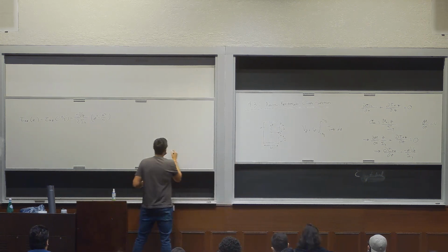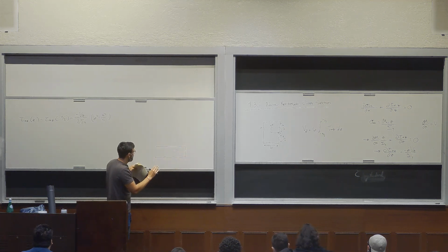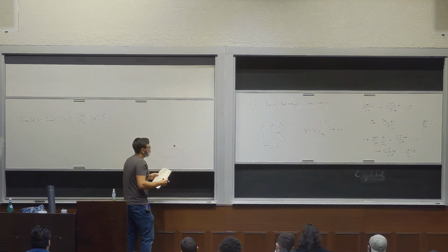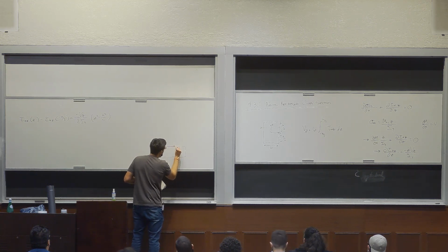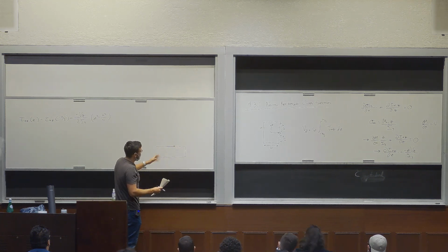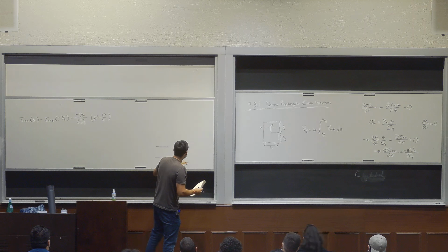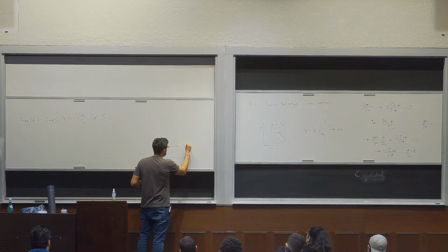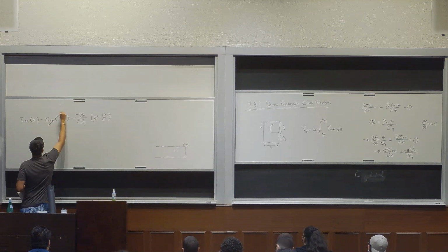Just because there's been some confusion about this as well: if this is the beam, looking at it from the side, regardless of whether the force is applied like this, there is no shear stress in that direction. In order for that to not be 0, there would have to be a force parallel to the top surface. But we haven't experienced a problem where that's the case, and such a loading is kind of weird. I don't think we see it in any one of these examples. So the top and bottom surfaces are considered free, so tau xz at this location is 0.